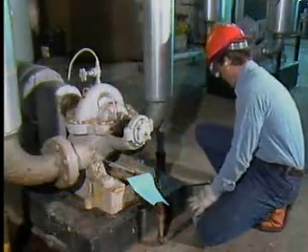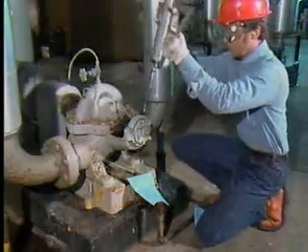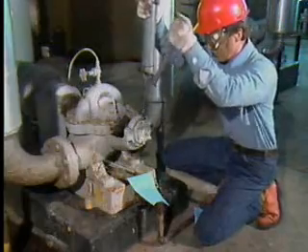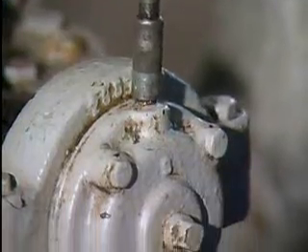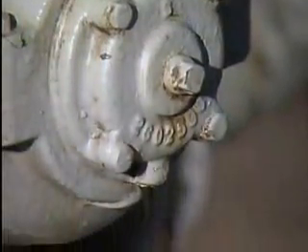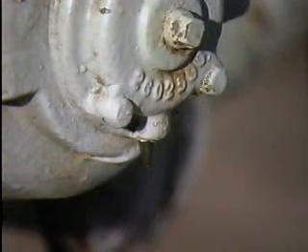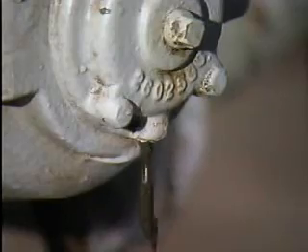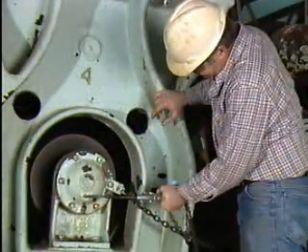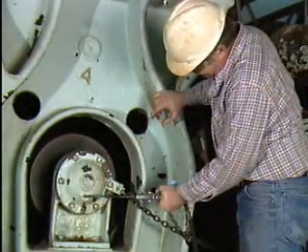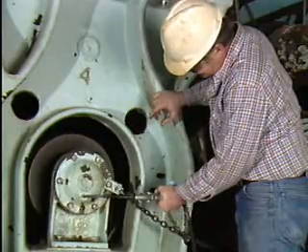To grease the bearing, a grease gun with a matching fitting is attached to the fitting on the housing. When this method is used, it is often necessary to remove the housing drain plug to allow old grease or excess grease to drain out as new grease is pumped in. Grease should be applied to the bearing while it is in motion to ensure that the grease will be evenly